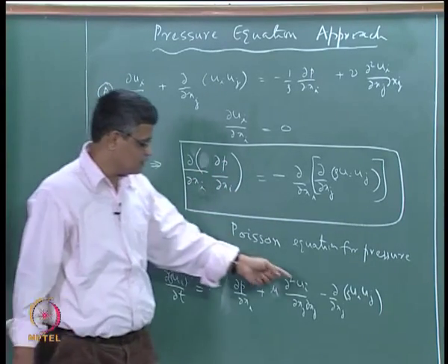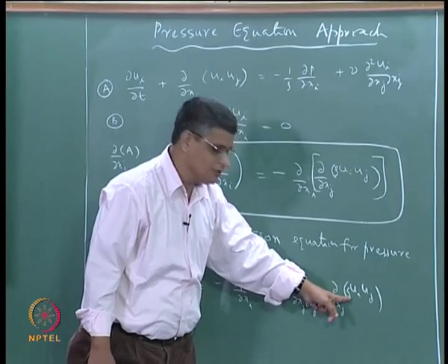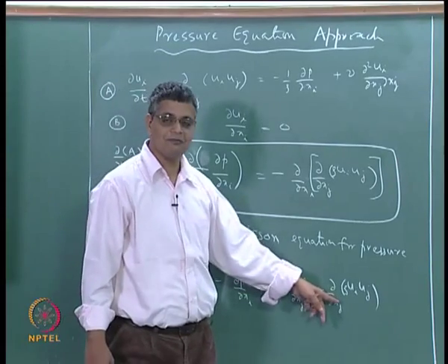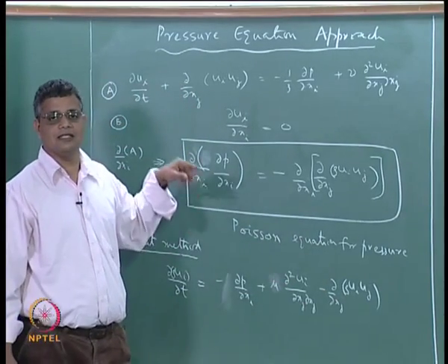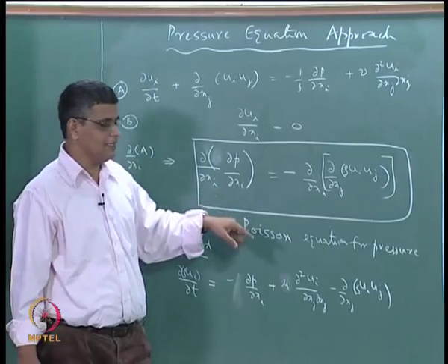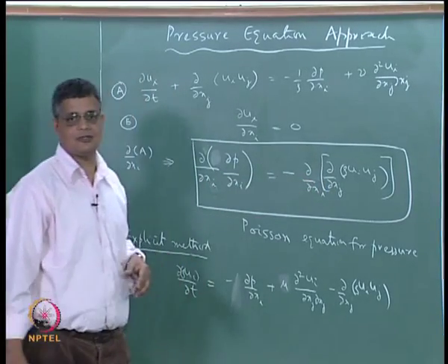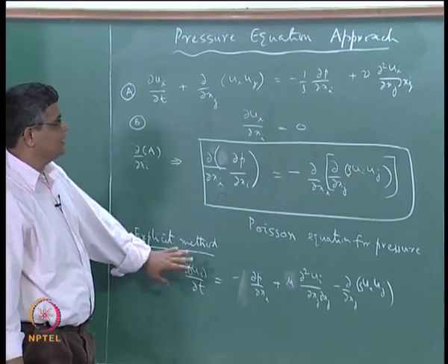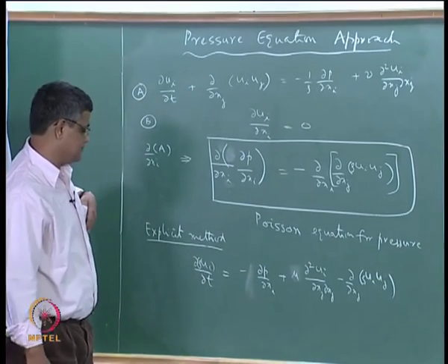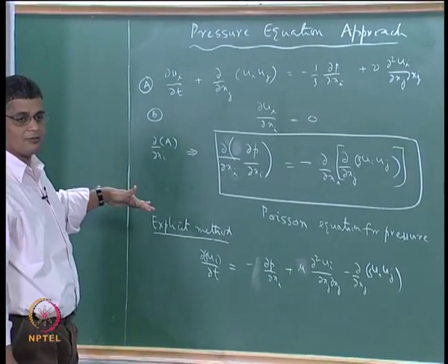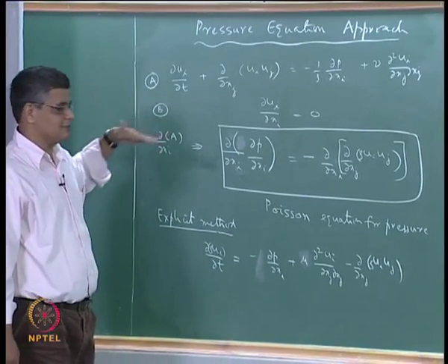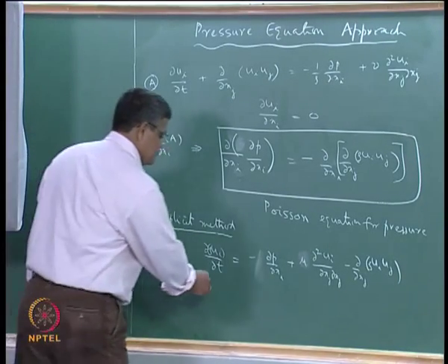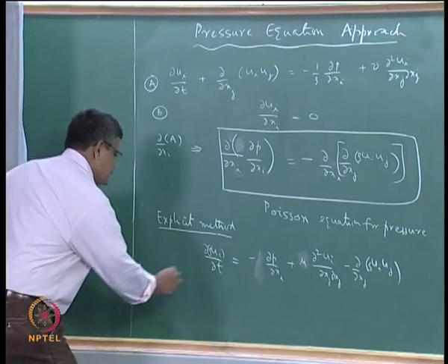Okay, so that is why there is one reason to put rho inside here, because that takes care of those kind of situations where density variation is not arising from the compressibility considerations but from other considerations such as compositional changes. So we can put it down without loss of generality, without affecting the assumptions that we have made in terms of incompressible flow and the time step limitations for stability and all that. So we put it like this, and we can make use of a discretization, and we can say that